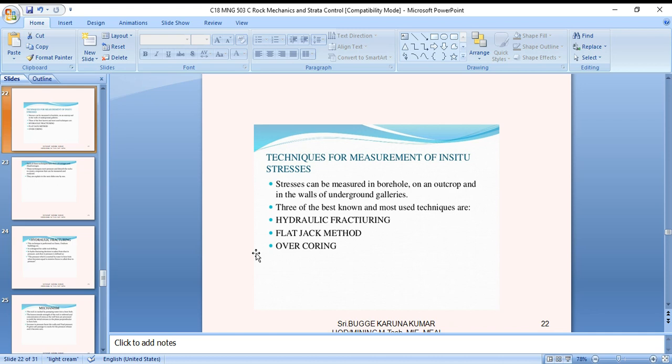The devices are available in a variety of sizes, with different displacement measuring ranges. So the transformer consists of primary coil and secondary coils, within which there is a movable iron core supplied in the primary, and if the iron core is centrally placed, the voltage in the secondary coils is equal and opposite.